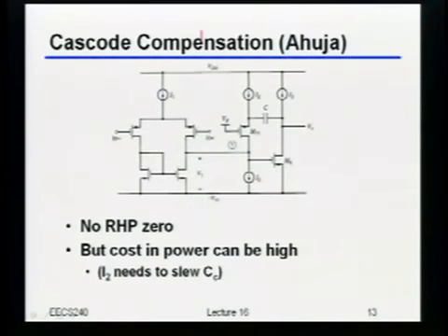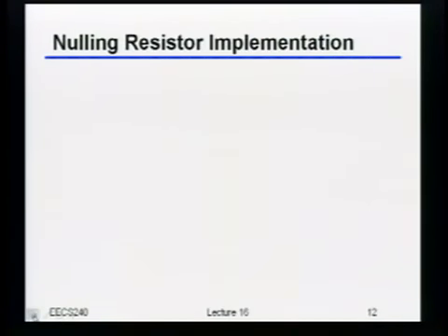So last time we were talking about multi-stage amplifiers, specifically two-stage amplifiers. We'd gone through and discussed all the different stability considerations. And where we basically ended up was looking at using nulling resistors to get around some of the issues introduced by using the Miller compensation technique. Just to remind everybody, if we have a two-stage amplifier and we just use a simple Miller capacitance, then a lot of times what you end up with is that feed-forward zero ending up close to somewhere that you care about from a stability standpoint. So we said that we could add a resistor in there to try and null that feed-forward zero out.